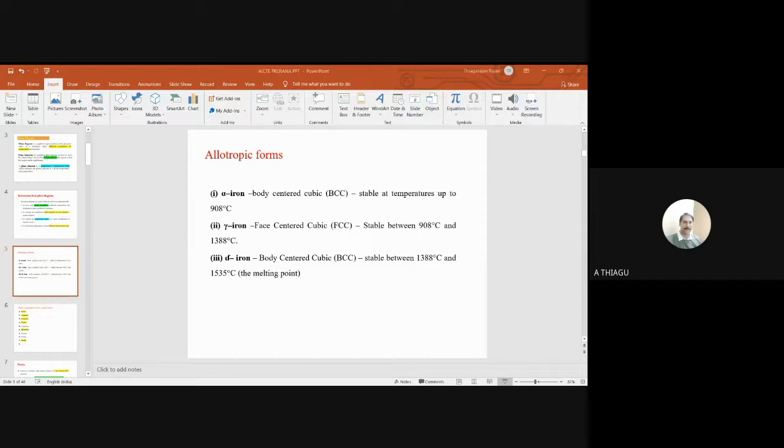Now look at the various structures. In some cases we have to understand the structure of the material, how the lamellae are formed or how the carbons are present. In most cases you can see grains having the same uniformity. If you have white appearances with uniform grains, it comes under ferrite material because it has little carbon. And in some cases we can see the structure having different grains. You can see the changes.